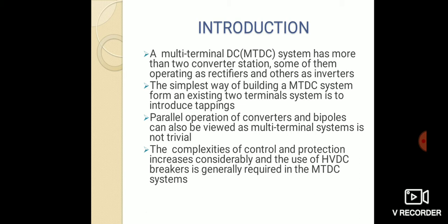The simple way of building an MTDC system is from an existing two-terminal system. They are introduced as tappings and by parallel operation of converters and bipoles. They are viewed as a multi-terminal system. It is not trivial. The complexities of control and protection increase considerably, and the use of HVDC breakers is generally required in MTDC